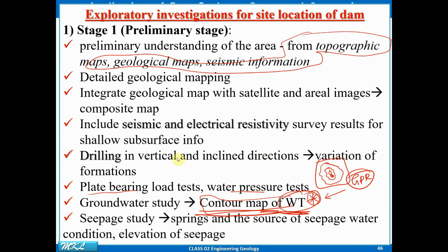Another study you will be doing is the seepage study. So springs and sources of seepage water, what is the channel orientation, where the lineaments are and how they are oriented, how the riverines are oriented, how the seepage waters are passing through a faulted area or a microfracture area. So that study you should be doing. That will be your stage 1.